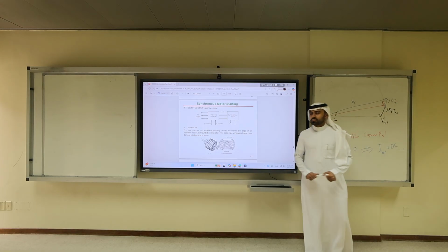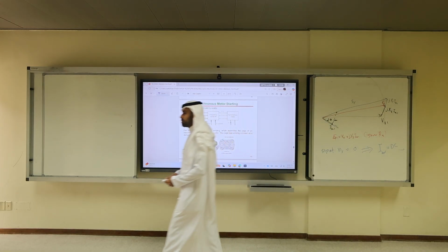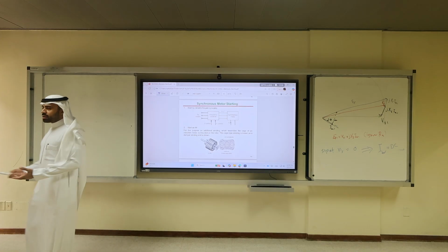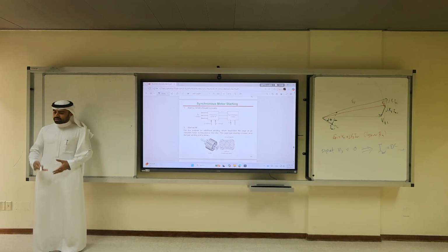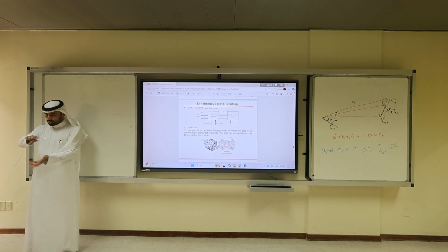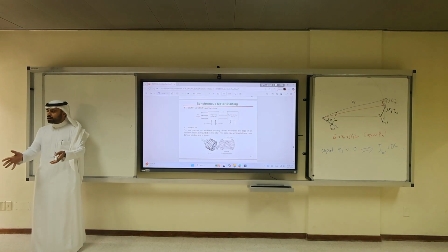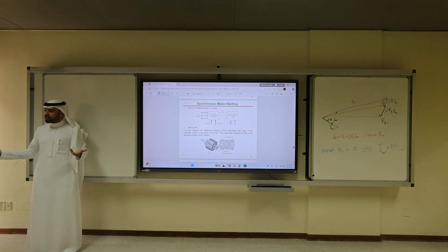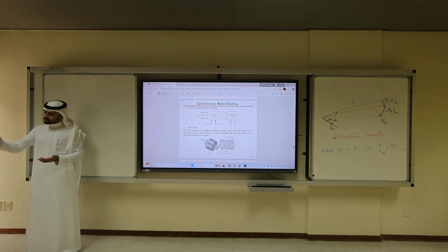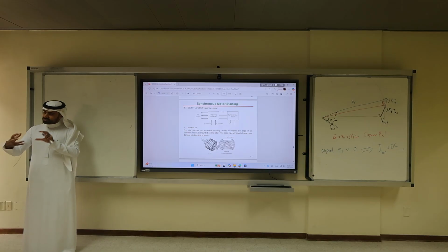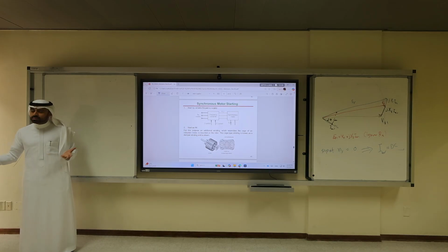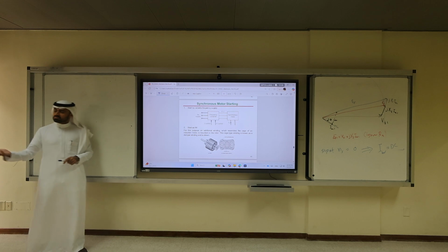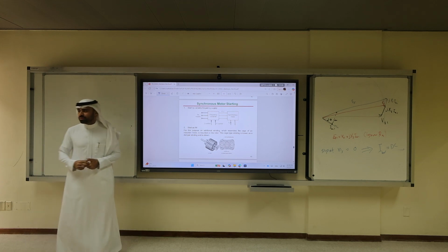No, it will draw more current to rotate the same rotor. If it's heavier, the inertia is higher. The stator magnet has to do more work. Nothing is free. So that's one of the downsides, you add more weight to it. But sometimes for EVs this is not a problem.